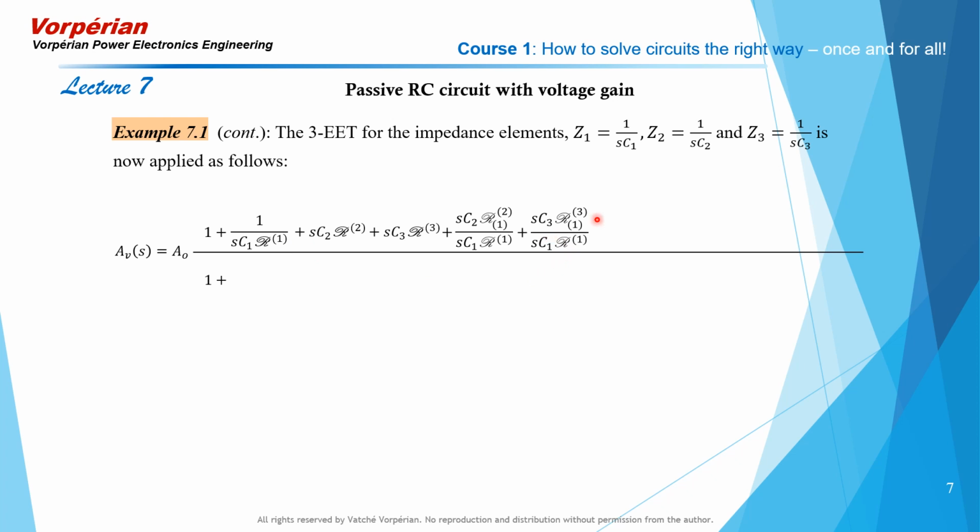Next, we reinstate 1 and 3 together. 1 comes in as it was again, as though it came all by itself. Then it is being paired with 3. When 3 comes in, the third element comes in. The null impedance looking into port 3, again, is going to be computed with port 1, the port with which it is being paired, in the opposite state of its reference state. And the same goes for pairing 2 with 3.